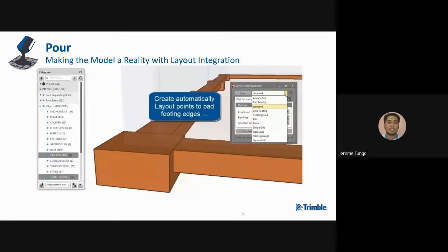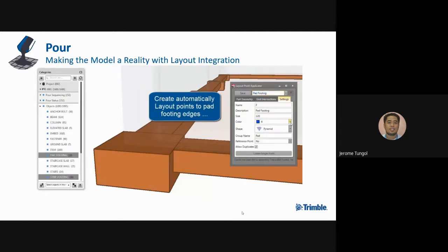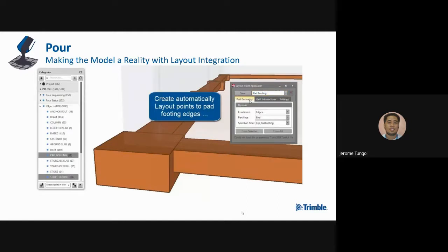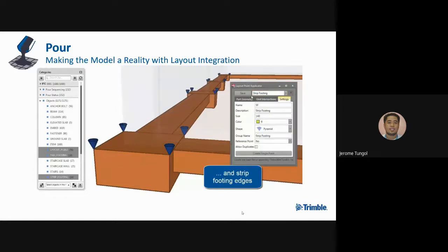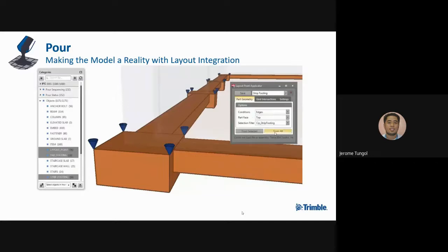layout points. So Tekla Structures is capable of providing layout points in the model using point creator. We can easily select desired parts with organizer and then layout points are automatically created on the selected parts. You can input names in layout points for better groupings.